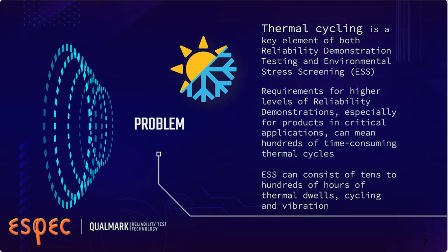If you have Class 1 devices, they say 300 thermal cycle tests are necessary for validation. If you have a Class 2 device where you have high performance and extended life requirements, you can be looking at up to 700 thermal cycles. That takes a whole lot of time. Fortunately, there's ways to speed that up.